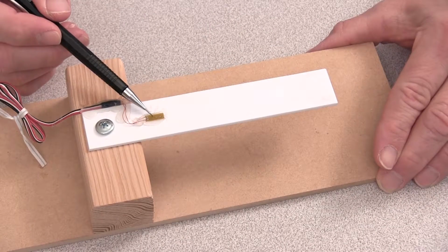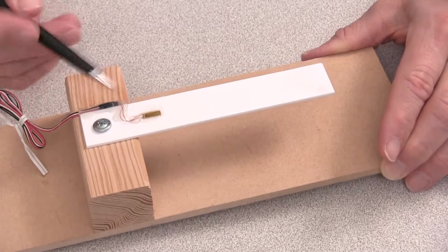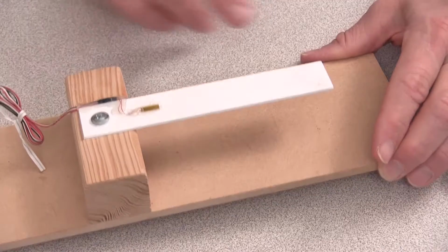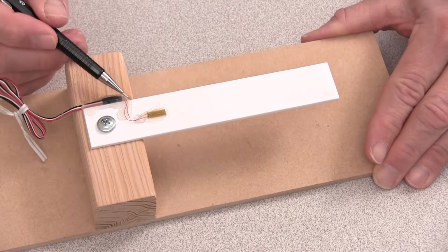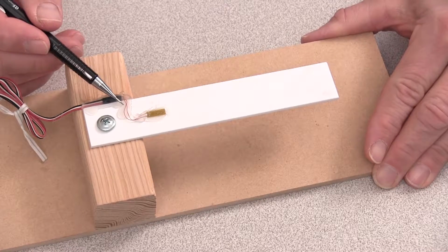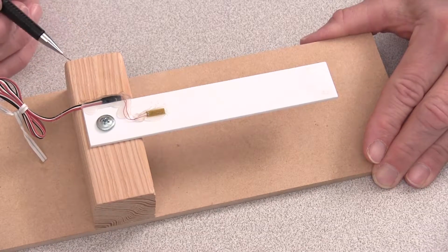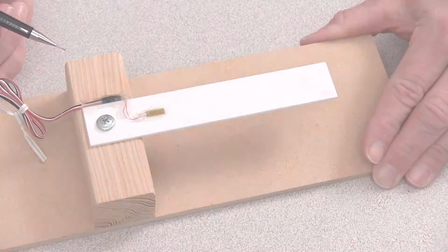I'll use a strain gauge to measure the deflection of this plastic beam. I've simply glued the strain gauge to the beam here. For this system, our input will be the deflection of the tip of the beam, and the output will be the resistance change of the gauge. Before we take the data to characterize the system, though, let's talk a little more about the system itself and why strain gauges are useful.